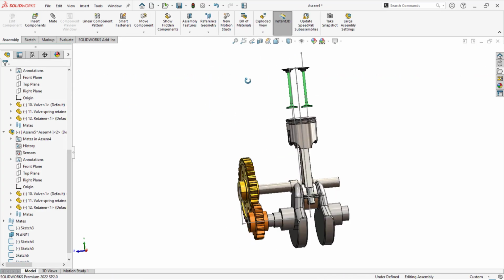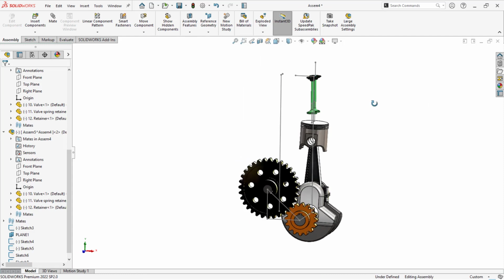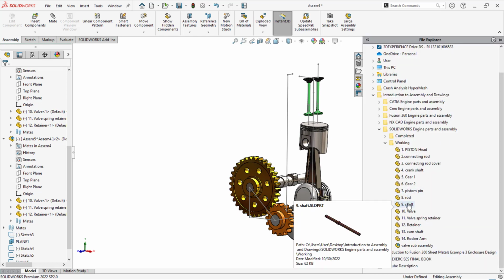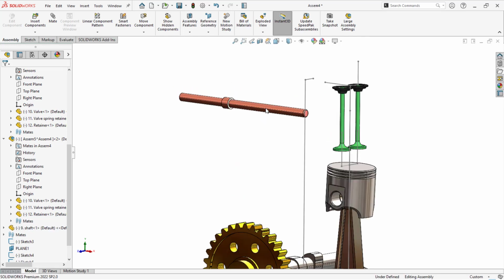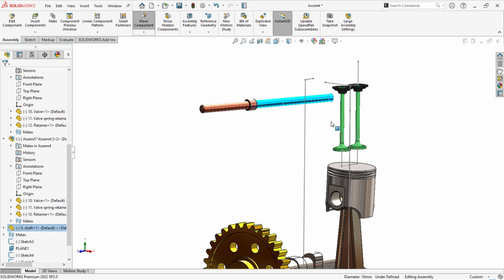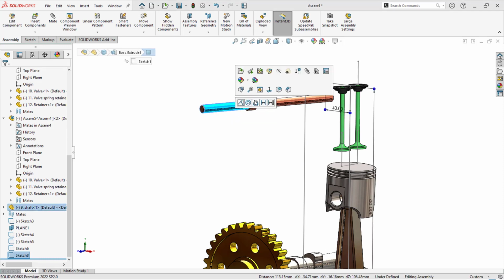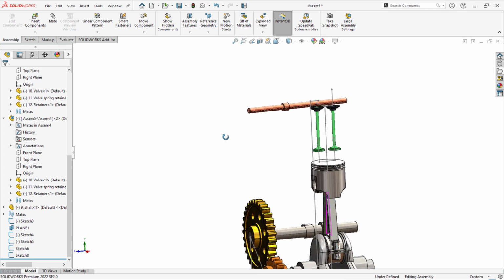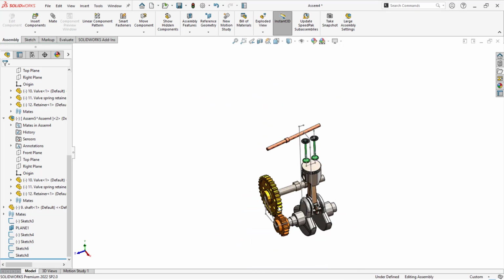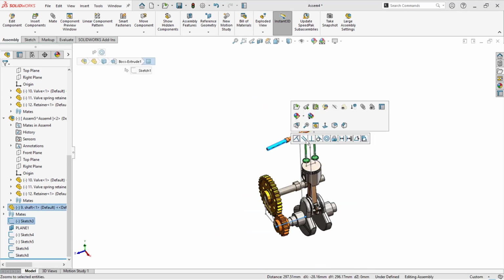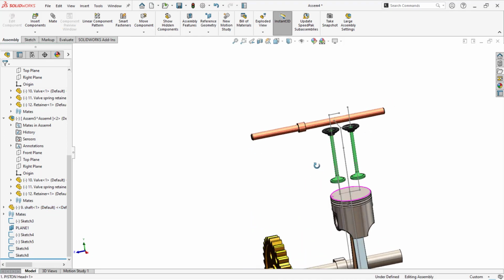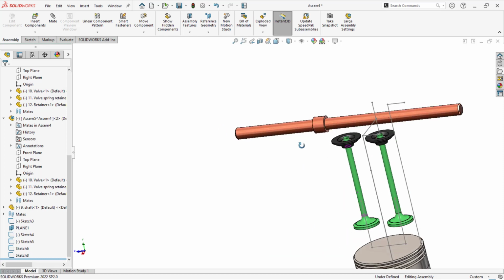This line should be vertical. Now why I need this is to add the shaft. So again I'll rotate it, and this point and the circular face concentric, but still it is moving. To restrain or constrain this, I'll refer this line and this one parallel. Along with that only it will move, isn't it? Yep.